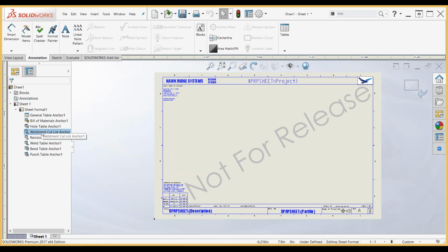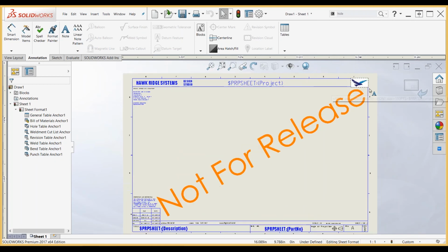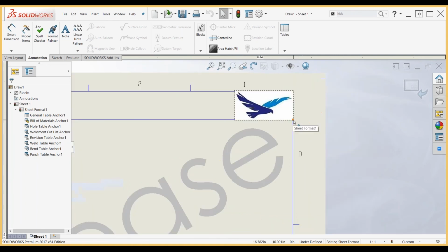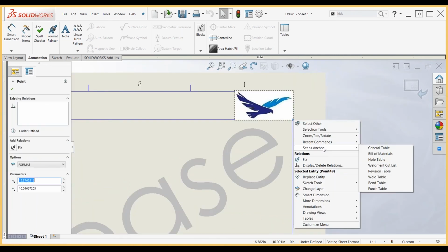So I have this cool option here called title block fields. I accessed it by right-clicking on the background, or you can search for it in your commands. What it does is create this area where I can make notes accessible from the default level of your drawing, so you don't have to come into the formatting.